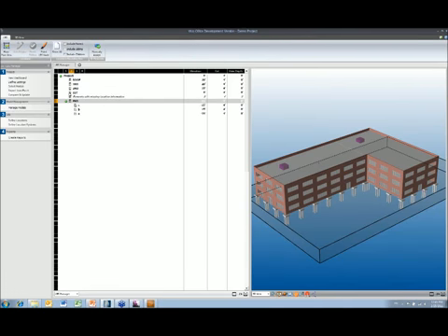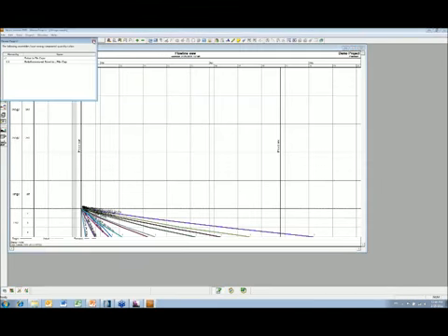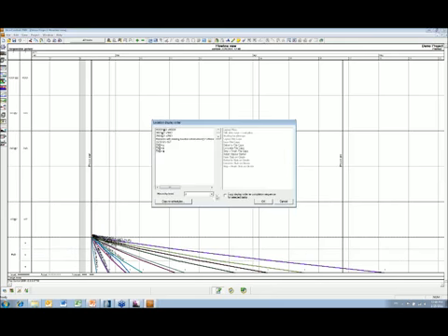So once I'm happy with my location structure, then back to my schedule planner workflow. Okay, it's got all the tasks starting at C first, so let me change those. When we have all these locations, we can easily create what-if scenarios by changing how the tasks flow through the locations, working our way around the building, and we've got lots and lots of flexibility to be able to do that.